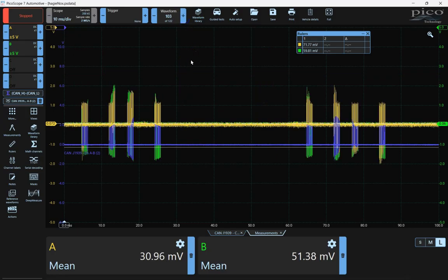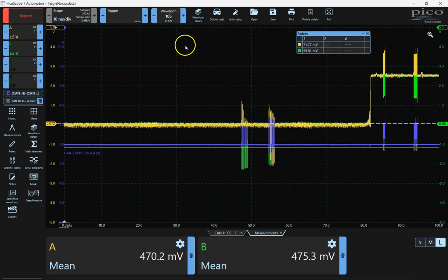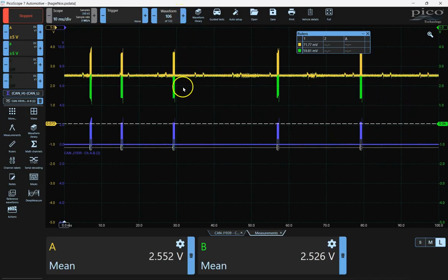The whole waveform here, 10 milliseconds per division. This is a tenth of a second. It's very, very short in duration. So very long for the engine controller and missing messages from controllers, but this was our issue. Unfortunate for the technician, he had been messing with this for several days, had replaced both NOx sensors, I think even changed the engine controller and maybe the DEF header.